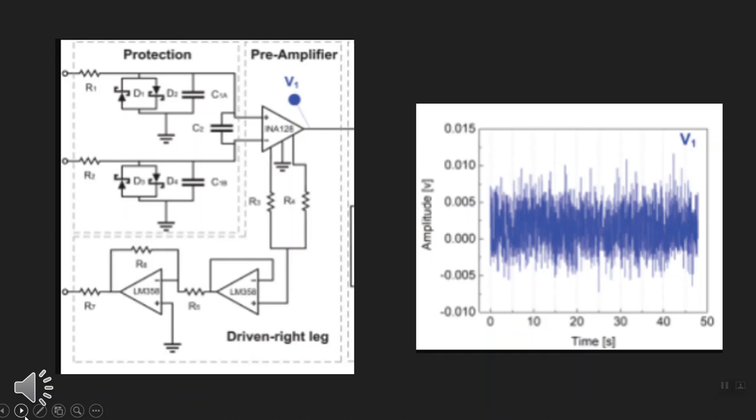In order to further reduce noise, a low-pass filter was added at the inputs to suppress the effect of high-frequency noise. Additionally, 2 Schottky diodes in the driven right leg were added to protect the user from electrostatic discharges and over-voltage peaks, which could be very dangerous. Next, the signal was amplified to get maximum gain before continuing to get filtered. This was done by being put into a non-inverting operational amplifier.